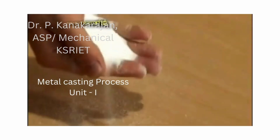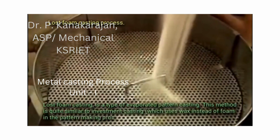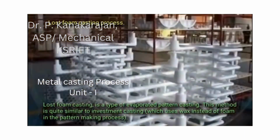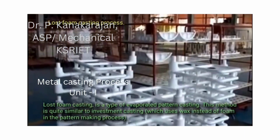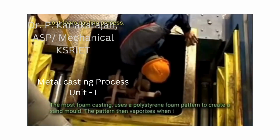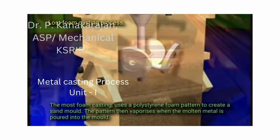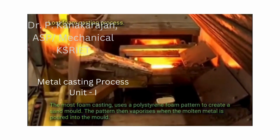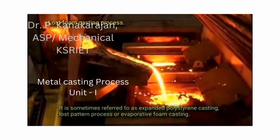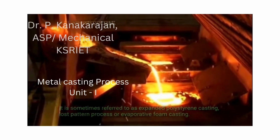Lost foam casting. Lost foam casting is a type of evaporative pattern casting. This method is quite similar to investment casting, which uses wax instead of foam in the pattern-making process. The lost foam casting uses a polystyrene foam pattern to create a sand mold. The pattern then vaporizes when the molten metal is poured into the mold. It is sometimes referred to as expanded polystyrene casting, lost pattern process or evaporative foam casting.